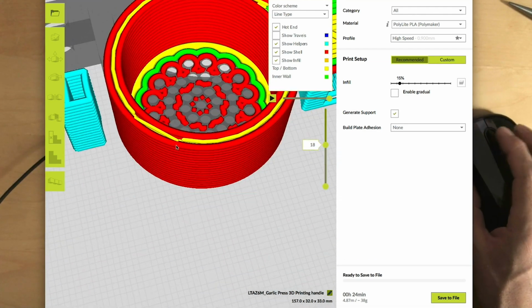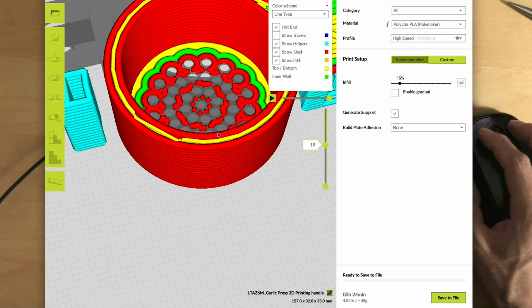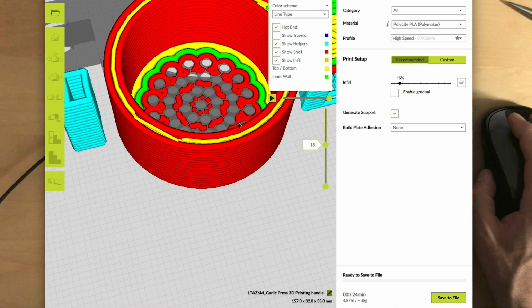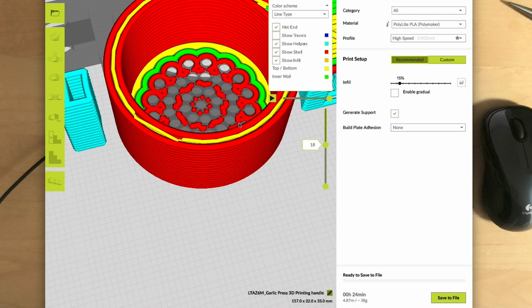And so this red line is one print, then there is something in between, and there's the next layer. So the nozzle actually can print 1.2 millimeters wide. Ideally you want to make your models or the shells as wide in equal increments as the printer can print. So let's say you have a nozzle that prints 1 millimeter.